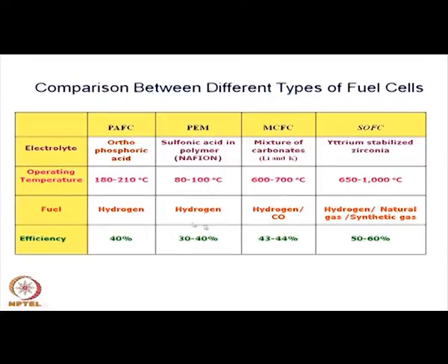Actually, when people started using solid oxide fuel cell, the temperature of operation was quite high, about 900 to 1000 degrees centigrade, and because of various kinds of research and the discovery or development of different materials, the temperature is coming down slowly. Currently, it is about 650 to about 800 degrees centigrade, mostly 800 is the limit now. Still, research is going on whether the temperature can be further lowered to about 500 to 400 degrees centigrade.